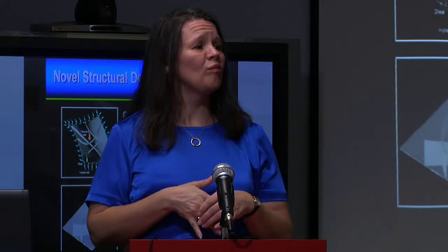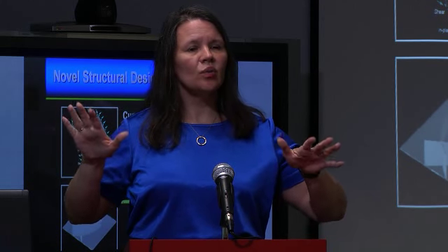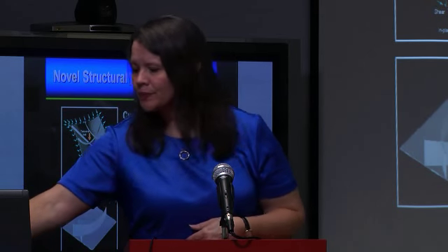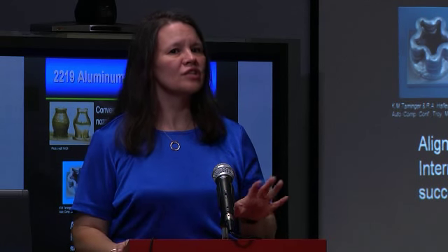What we're looking at doing now is tailoring the stiffness of the material along the wing, which helps us with flutter problems. Have you all seen the video of the Tacoma Narrows Bridge that sets up the oscillation, and in a couple of oscillations the whole thing ends up in the river? It's flutter, a very common problem in aircraft wings, and it's a stiffness issue. And so if we can change the stiffness, we can try to eliminate flutter. Right now the way they do it, they add extra weight. There's one airplane that flew several years ago. They added 400 pounds of dead weight to help kill a resonant frequency. And so we're saying there's got to be a better way, because weight is fuel on an airplane. So these are some of the things that we're really interested in trying to do.